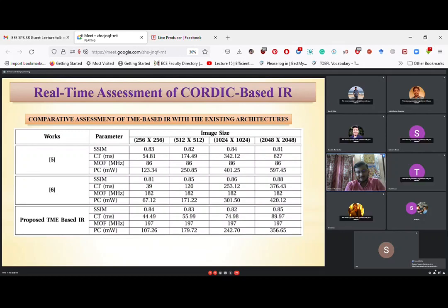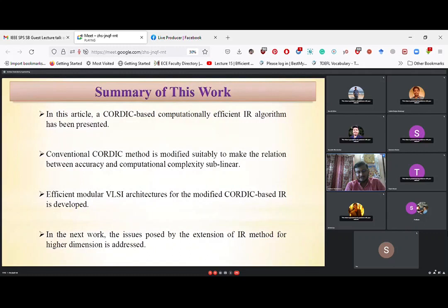First of all, for any hardware realization, you need to think of the complexity of the algorithm. And if you find the algorithm too complex for it to be hardware realizable, then you need to simplify it first. Like our image registration, we have simplified it by means of CORDIC. We have put the idea of applying CORDIC, that is the vector rotation, instead of each and every pixel rotation. So this intuition and idea you need to apply to make the algorithm hardware realizable.